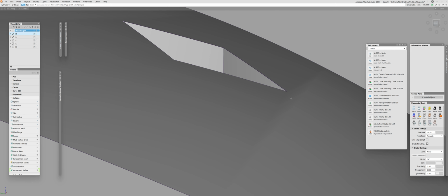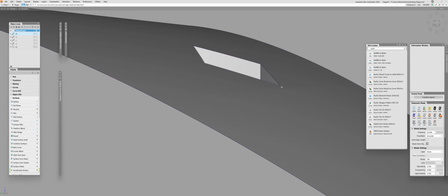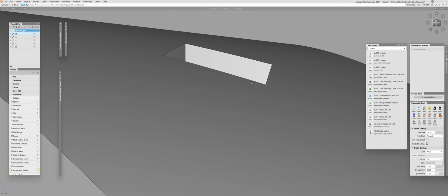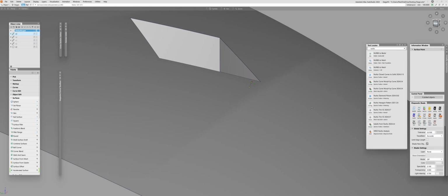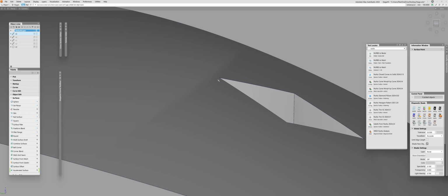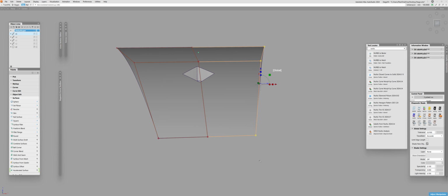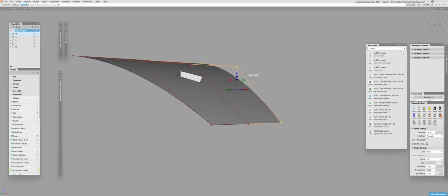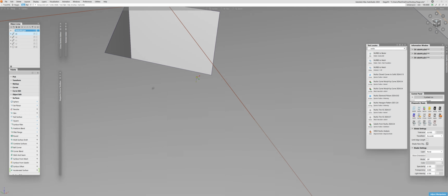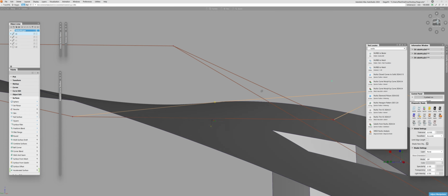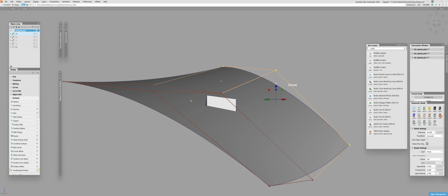Once again, it can be more or less prominent in the viewport of Alias, but it will exist. And in the actual modeling tools like Blender, Maya, and so on, it will be really prominent. It will look like an error. And in fact, it is an error. All this stuff is not great. Now, see what happens when I take this side. It's curved in one direction, and I will curve it here. Oh, look at it. There is no issue anymore. Why was that? Now it's curved on both sides.